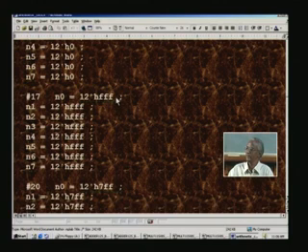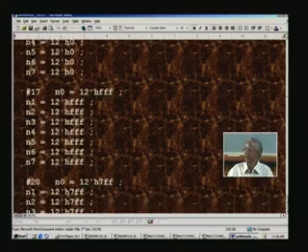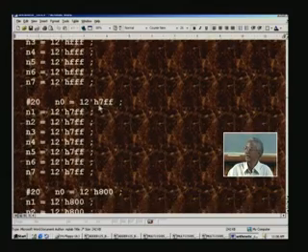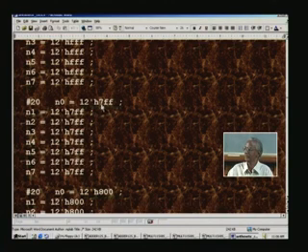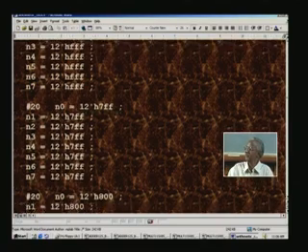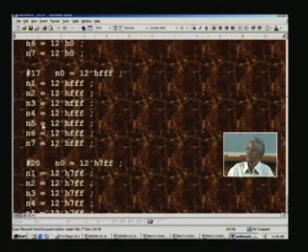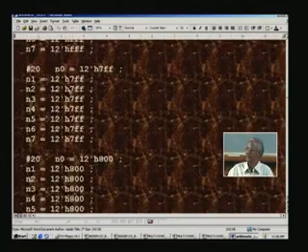All ones, as we have seen in 2's complement representation, is -1, and we are going to add -1 here, and all zeros here. And after 20 nanosecond we are going to change again to a different value. Here it is 2047 or something, which we will see when we look at the waveform. Initially we have staggered a bit here, 17 nanoseconds, just to make sure that data is stable before the clock arrives. And every 20 nanosecond we are changing here.